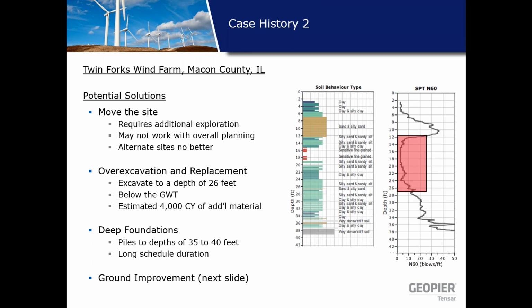In this case, you would have to go 26 feet, which results in an additional 4,000 cubic yards of material. Or you could put in deep foundations, which I anticipate would go down to about maybe 36 to 38 feet or so.